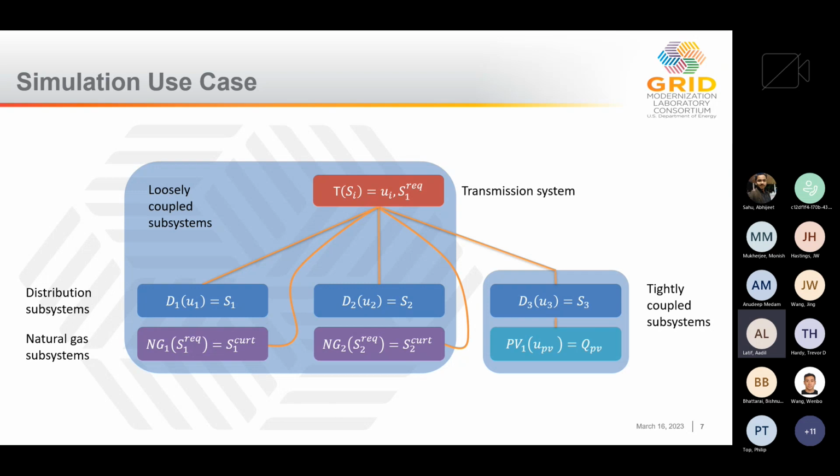So we're not dilating time and trying to do it that way. The simulation time stops there until we reach convergence, and then we move forward. Yeah, I thought so, because for one distribution system, you are waiting until the convergence takes place, right? So it's not a single snapshot, it is a multiple sequence of snapshots coming along, right? And that is also independent of scenario when the number of iterations may vary, right? Yeah, that is correct.